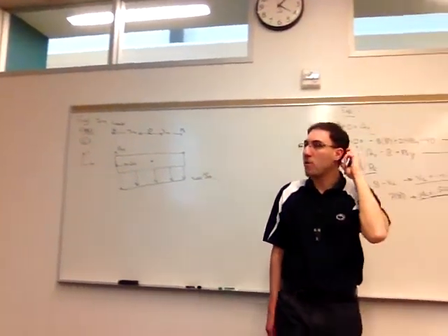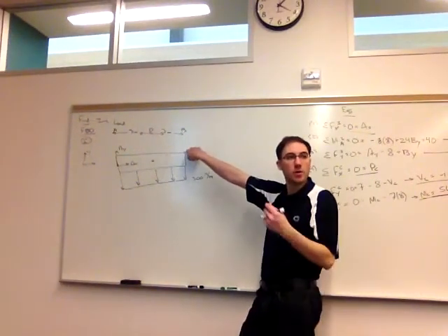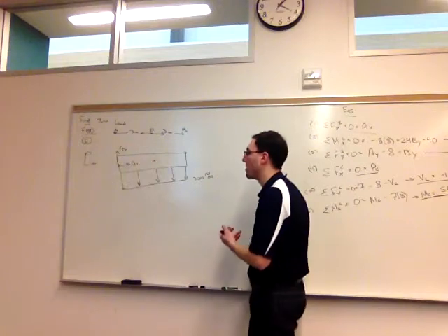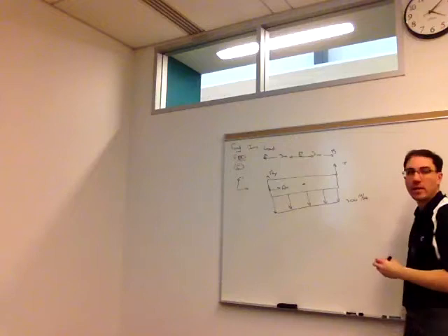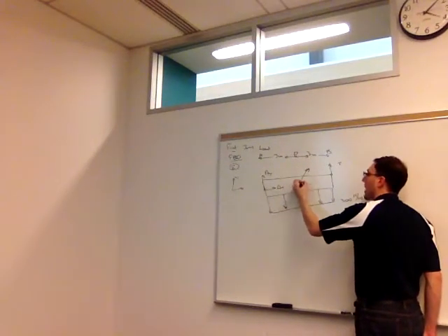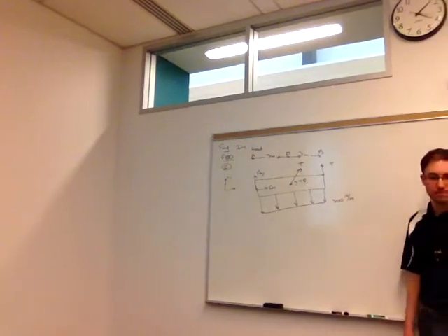And we have a rope that goes from D over a pulley back down to B. So it's one continuous rope. So when it's in static equilibrium, the tension in the rope is constant. So we'll have some tension pulling up at B, and then that same tension pulling at a 45-degree angle at point D.